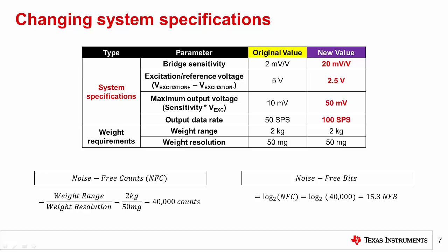Moreover, you would have to recreate the datasheet noise table at a reference voltage of 2.5 volts, since the original table is characterized using Vref equal to 5 volts. The new reference voltage reduces the ADC's dynamic range performance by 1 bit compared to the datasheet. Finally, you would have to subtract each resolution loss from your new, recreated noise table and compare it to the target specification as we did on the last slide.